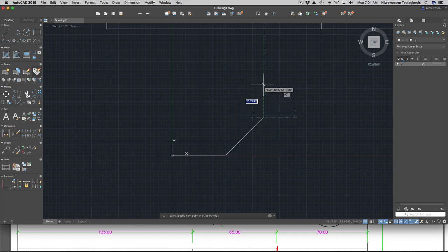And the second one, along here, is fine. You can just simply type 50, and there I have the line. Then to go in this direction, look, the angle is not 45, because since it's an engineering tool, mostly the angles are measured in the counterclockwise direction. If you follow, you see the angle is increasing to 60 now, to 90, and then you pass that 90.